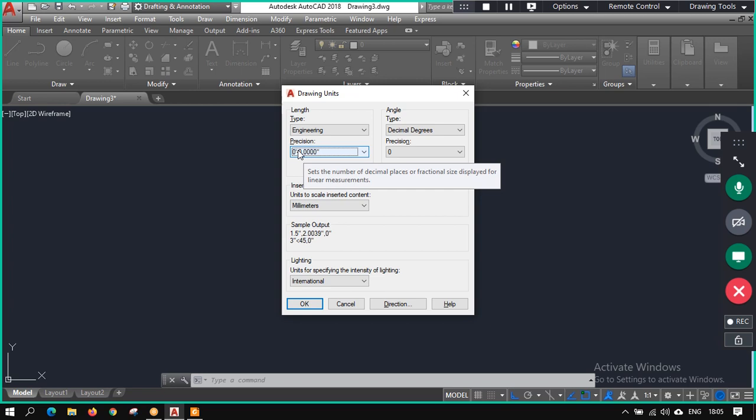Okay. Now, one more important thing: there are a few AutoCAD installations where you have to select the unit system during installation. If you don't select it and leave the default, they will give you the full FPS system. They will not give you the SI or MKS system. It is because it's US based company software, so you have to take it as granted. For them FPS is the main criteria.